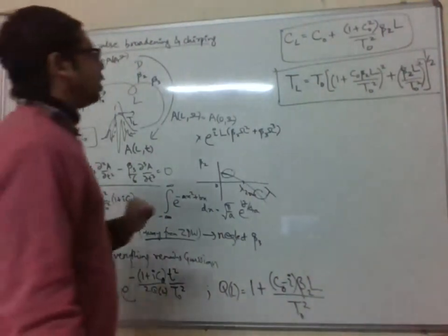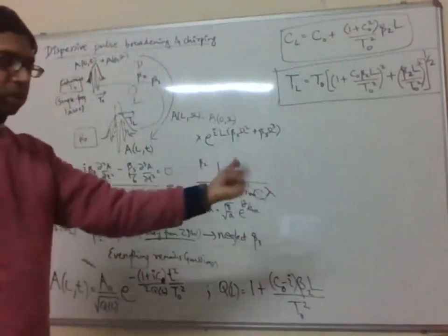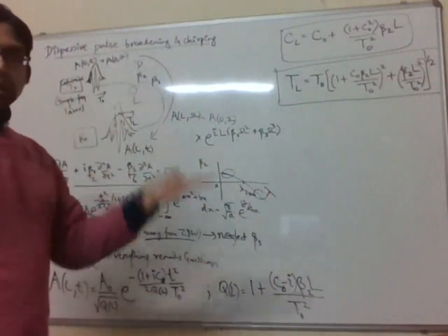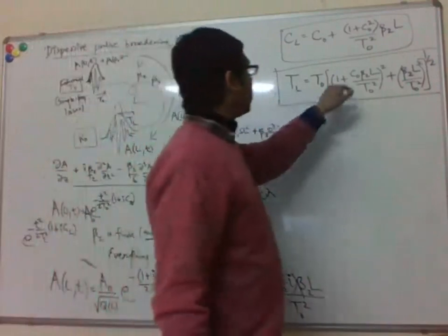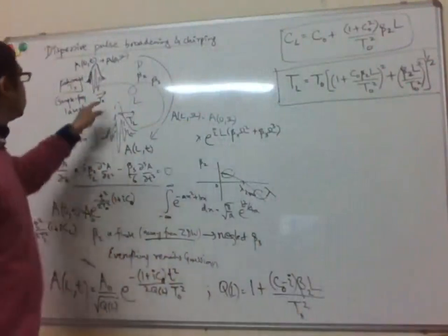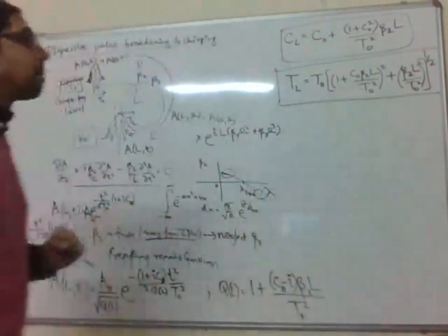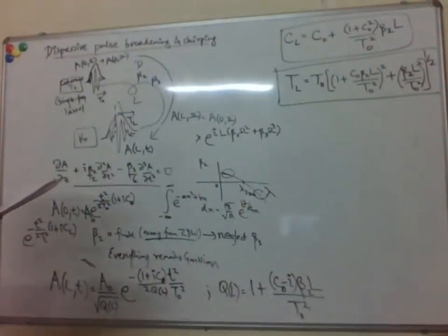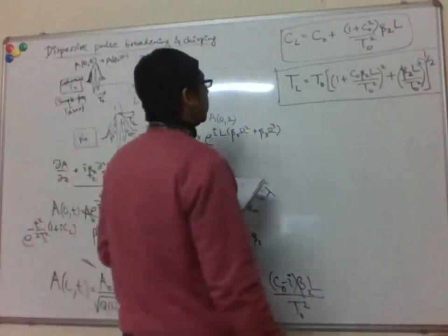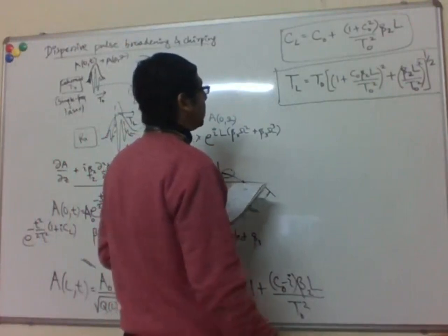Okay. So this is going back to the fact that we discussed. From that initial formula of the broadening being proportional to the source bandwidth, if we just keep reducing the source bandwidth to 0, does that mean the broadening just goes down to 0? It doesn't, right? From here, once your line width goes below the data rate or 1 over T naught, then T naught itself starts limiting you.